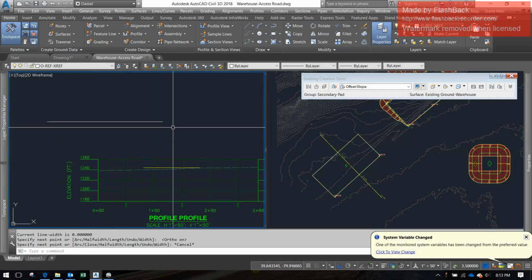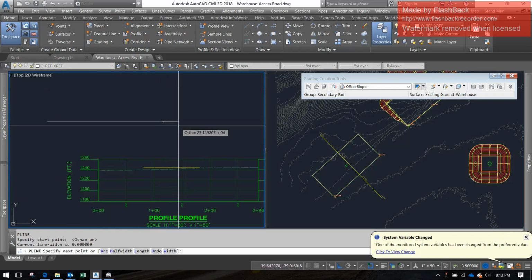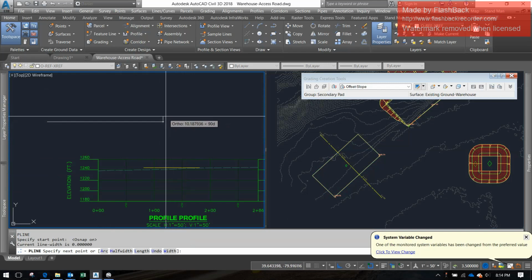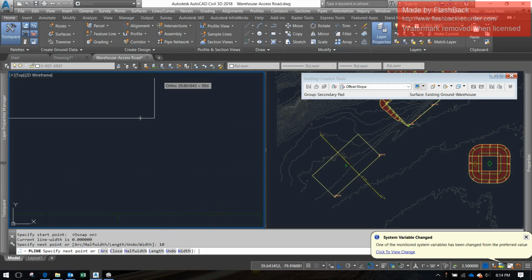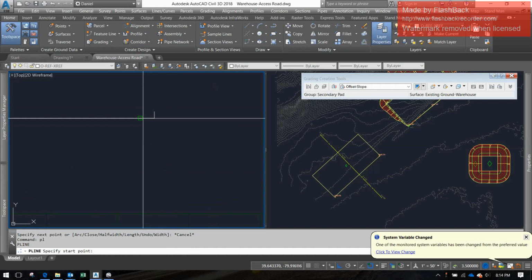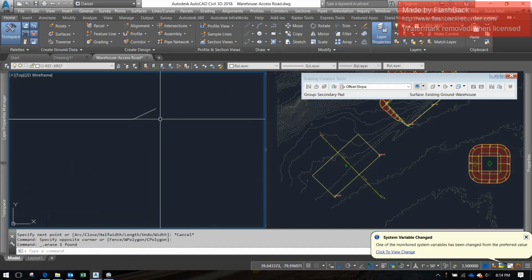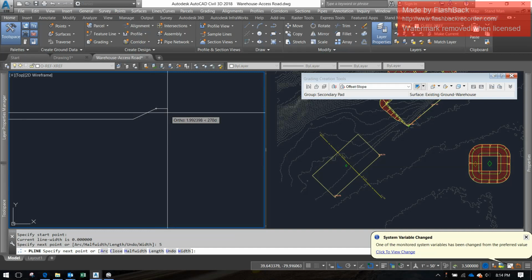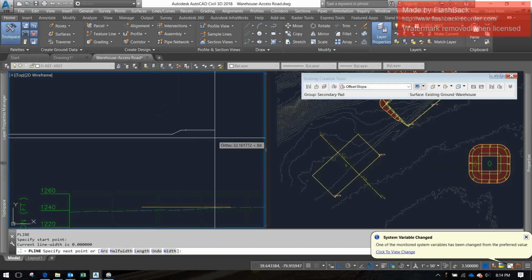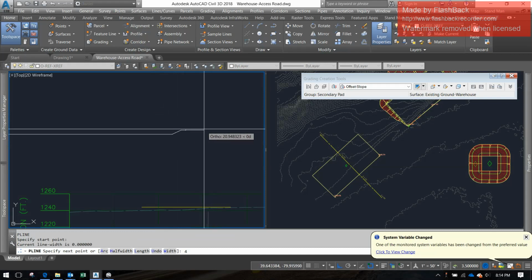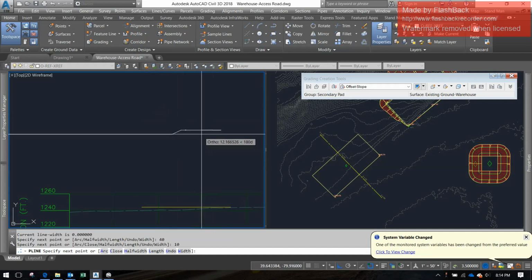So I'm going to have my flat pad here, and I'm just drawing this out for the sake of discussion. I'm going to have a 10-foot wide side slope on the outside at a 2-to-1 grade. So I want it to be 10 foot wide, and a 2-to-1 is going to make it 5 feet high. So I'm going to have a side slope that does that. Then I want a 5-foot flat top portion, so it's going to look like that on top. And then I want to grade down at a 4-to-1 again and see how that works. I want to keep 4-to-1. So what that means is that I'm going to go out. It's going to look something kind of like this.